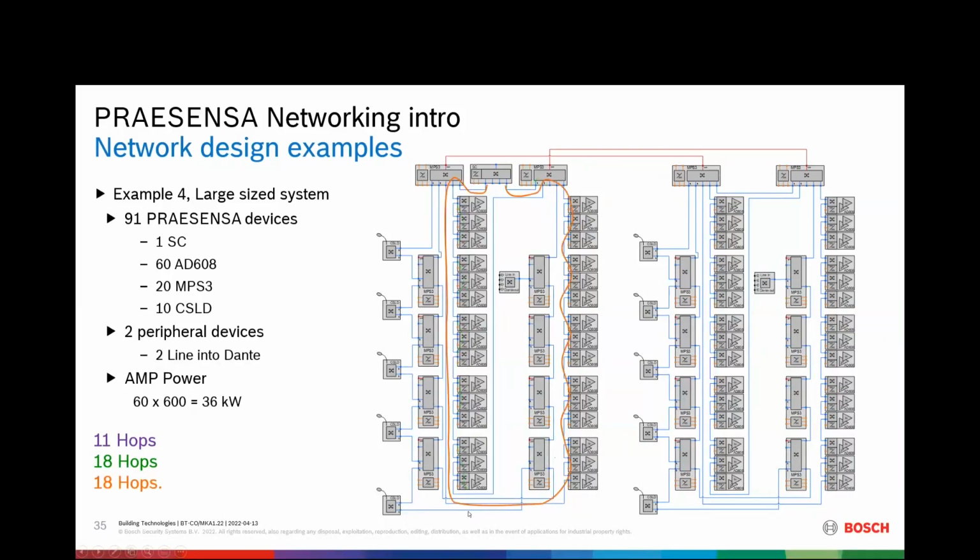So these are again 18 hops. Then we have from this MPS all the way down to here, and then not again through this, but directly back to this MPS. So with that, also keep it up to the limit of these 18 hops. And this side is exactly the same. You have one additional hop, because this is 1, this is 2, this is 3, and there you have your hop counts. It's not mentioned here, but it's still within the limit.